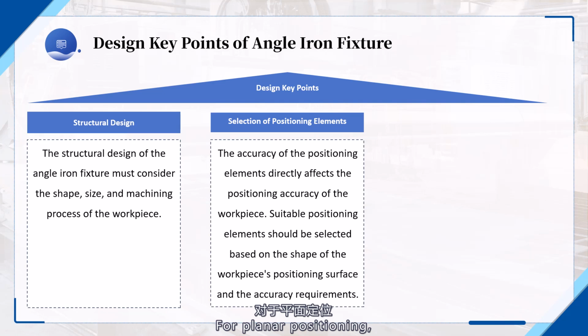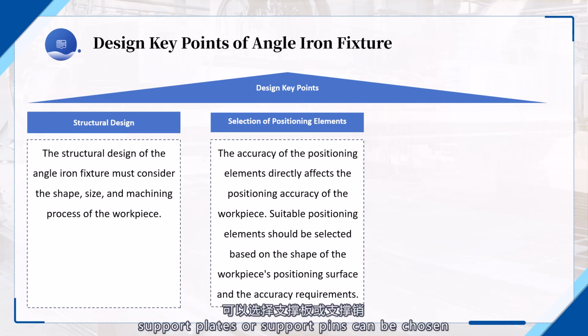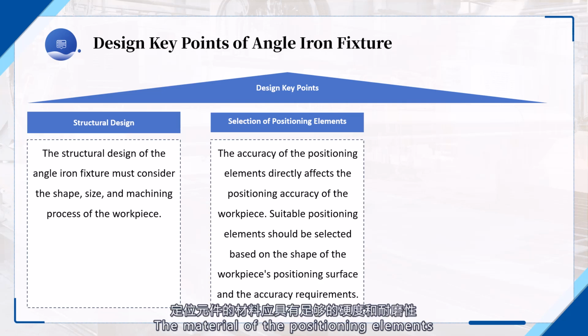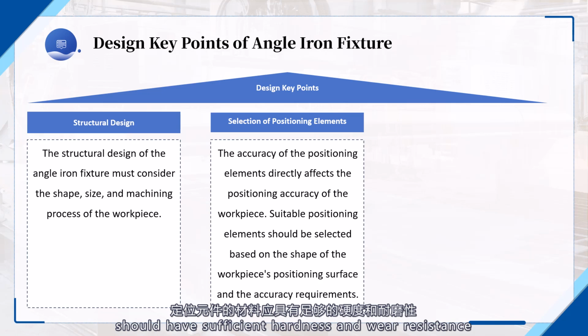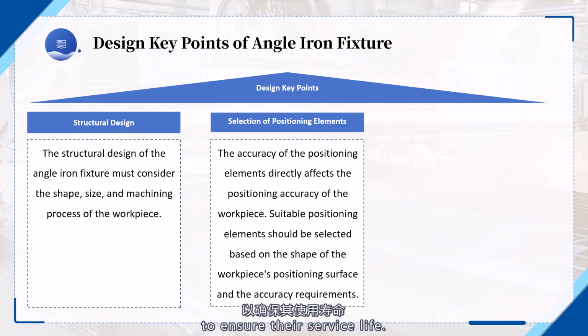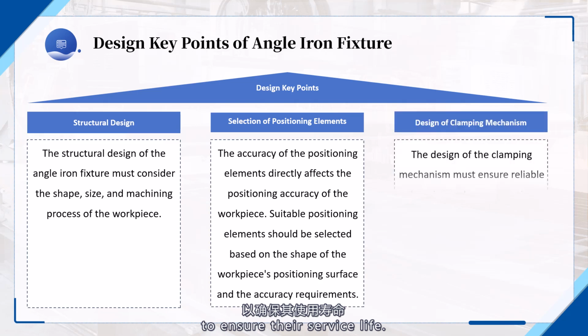For planar positioning, support plates or support pins can be chosen. For cylindrical surface positioning, V-blocks or cylindrical pins can be used. The material of the positioning elements should have sufficient hardness and wear resistance to ensure their service life.